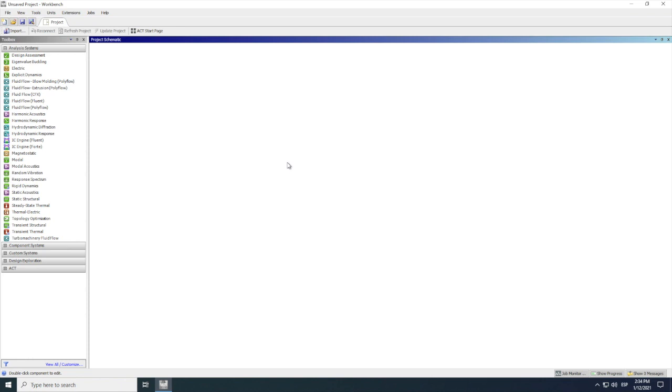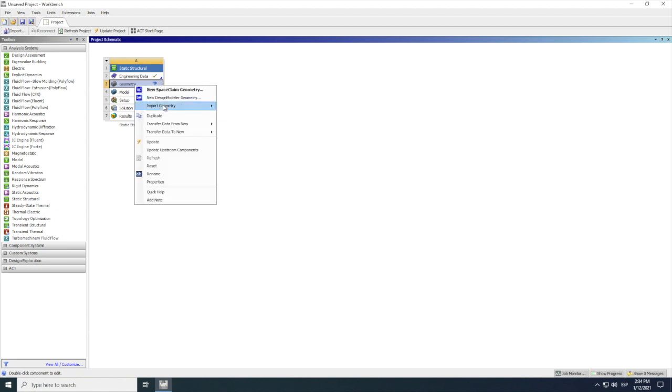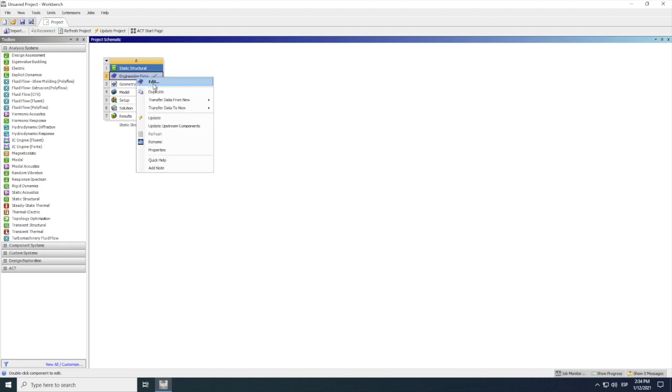So we're still going to use our SolidWorks file, which we saved as a STEP file. I'll show you in a moment. And we're going to begin with a static structural analysis. So we'll click there and we'll just drag it over to a grid window, which, we might want to zoom in like that. There we go. And when it says geometry, we're going to right click in there, import geometry. And well, I already have it like that, the white bracket dot step. That's how you should save it in SolidWorks. I'm going to give it like that. But before we proceed, let's go to engineering data.